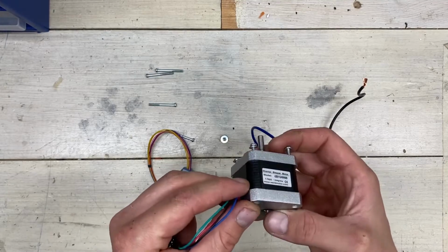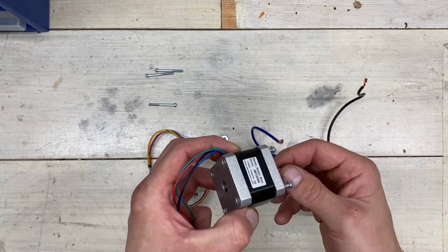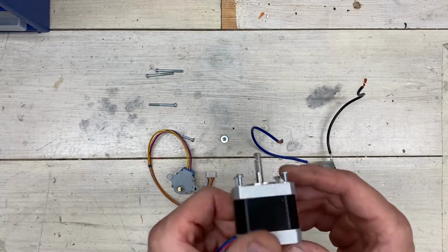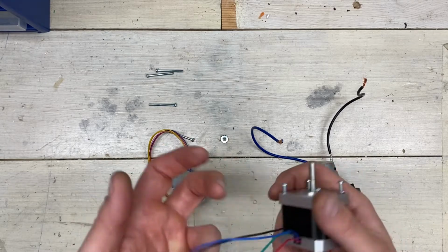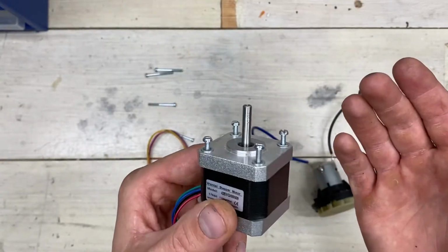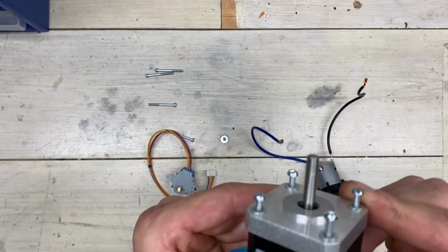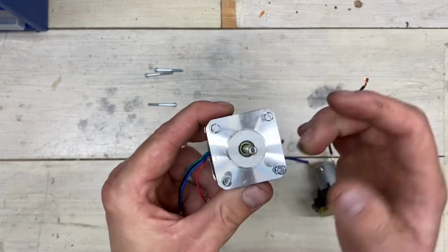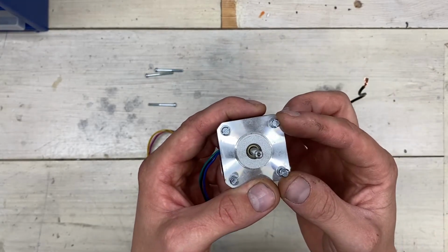Here I have another stepper motor, but a smaller one. The one I just showed you on my Queen Bee Pro CNC is a NEMA 23 size stepper motor. This is a NEMA 17 size. Now the NEMA sizes don't really have anything to do with power, but of course a bigger NEMA motor is generally more powerful. What they do tell you though is the flange size and the location of the mounting holes. So the flange size of a NEMA 17 motor is 42 by 42 millimeter, and the position of the bolts are 31 by 31 millimeter.